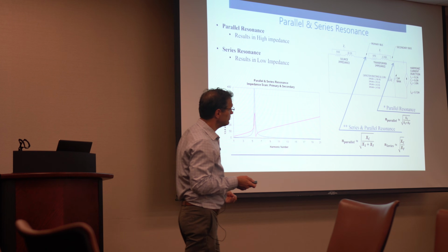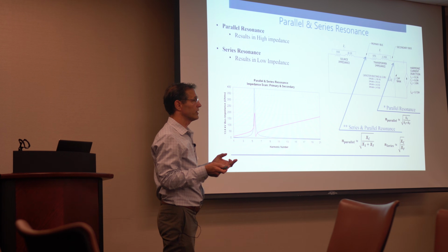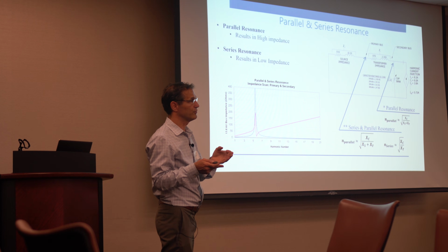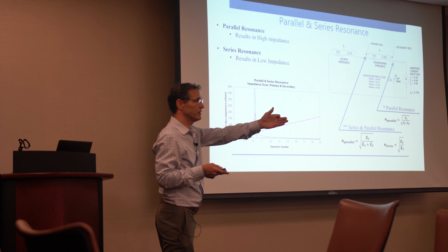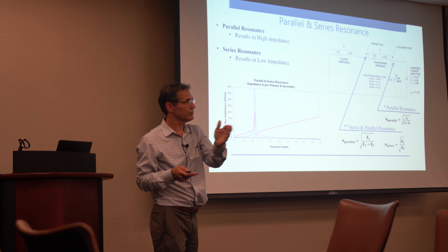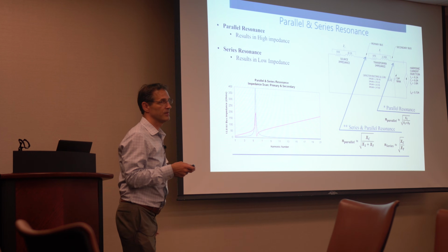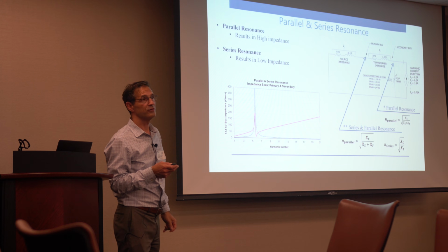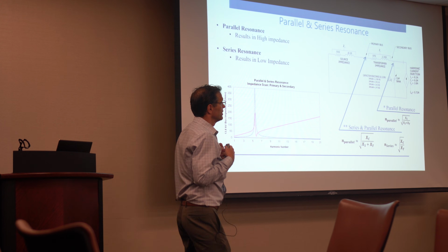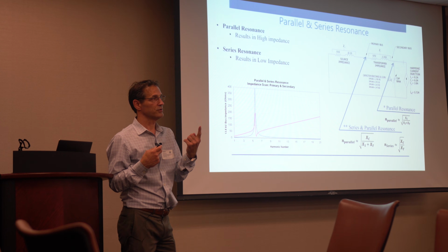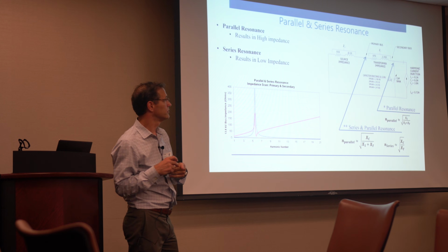The reason I bring this up is when you have a network, every time you add a capacitor, you add complexity. If you have a medium voltage network, a low voltage network, and a transmission network, and you add capacitors at each one of those levels, you're creating more complexity in your impedance scan. It makes it more difficult to design and to check that system. So I say do power factor correction at one voltage level. Pick your voltage level and do it all there. That would be a preference.